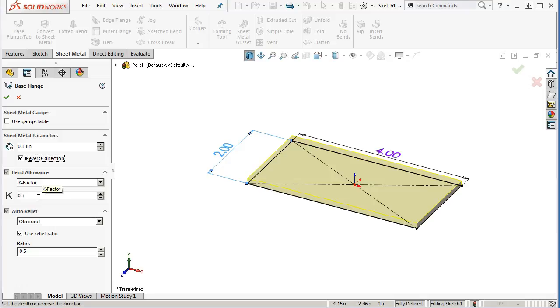As soon as I put a bend on that material, as the outside goes into tension, we're pulling it apart, and the inside goes into compression, we're crushing it, that K factor is shifting by some percentage. It's no longer halfway. And the steel, we found it to be about 0.25 to about 0.3. So that's why my K factor was set at 0.3.